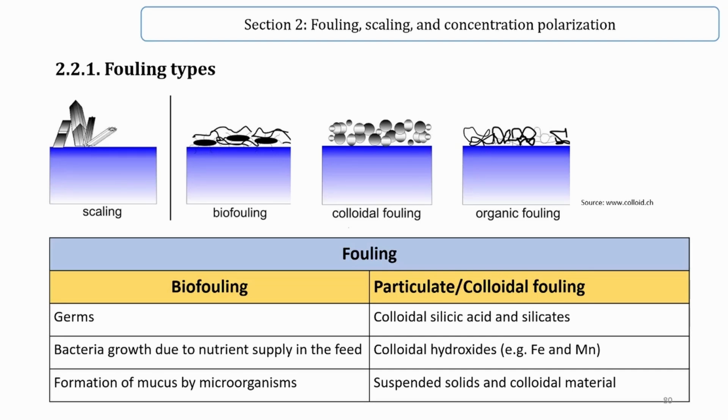In addition to flux deterioration, previous studies have shown an increase in salt passage in the permeate of reverse osmosis membranes followed by bacterial cells. The reduced salt removal rate is attributed to the biofilm-enhanced osmotic pressure phenomenon that hinders the back diffusion of ions, making them concentrated adjacent to the membrane surface.